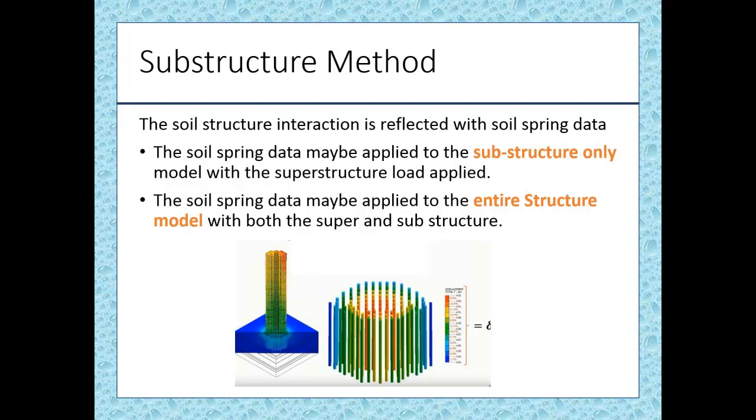Next, with this substructure-only approach, we are working with broken components of the whole structure in reality, especially when dealing with seismic analysis. The second one, the entire structure model, is the more common and more accurate approach if an engineer is using more advanced analysis tools like Midas Gen or Midas Civil.